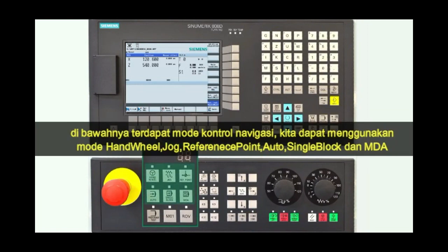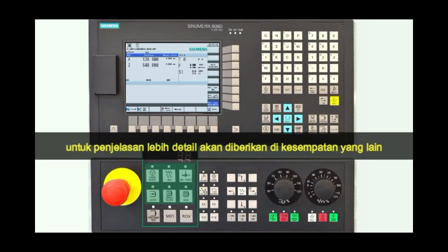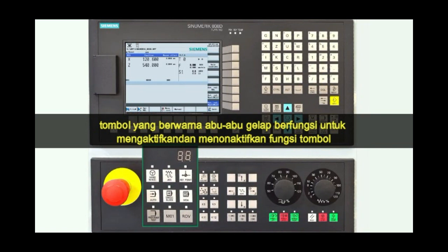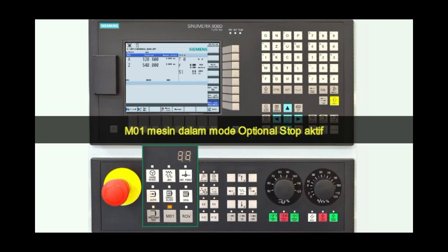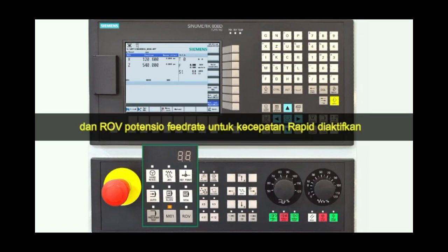Below there is the mode navigation of the controller. You can use the hand wheel, jog mode, reference point mode, auto mode, single block and MDA mode. Further descriptions will be covered later. The darker grey buttons activate and deactivate further functions. If the lamp is active with Program Test, the axes are simulated. M01, the machine is in optional stop mode, and ROV, the feed rate potentiometer is active for rapid movement.